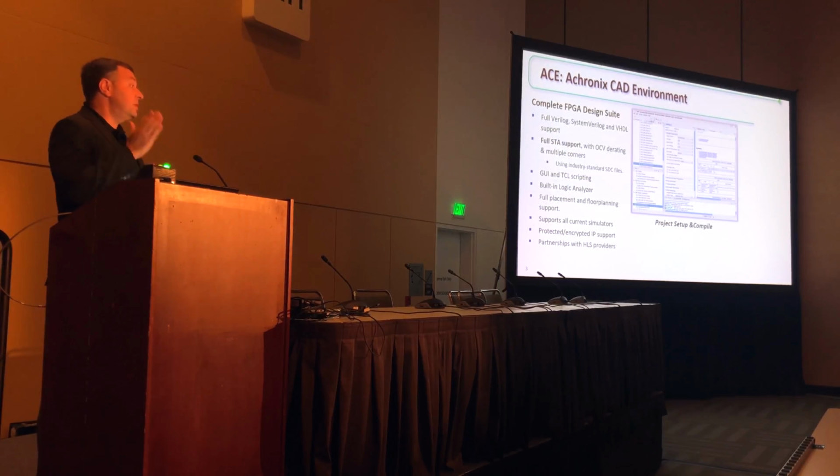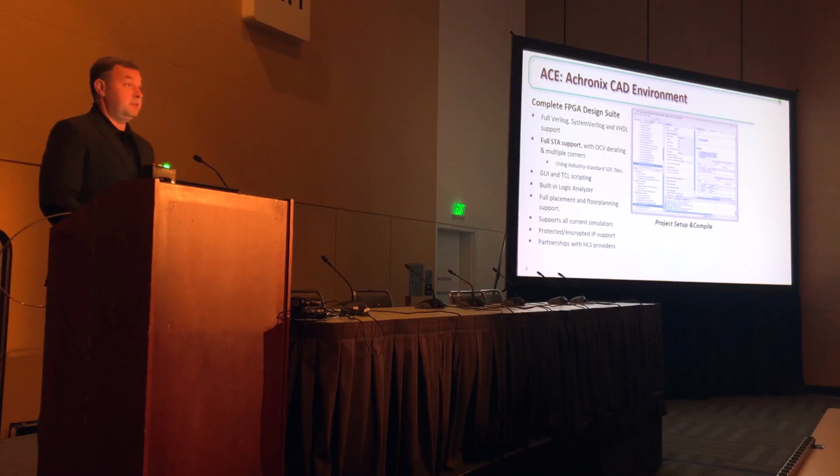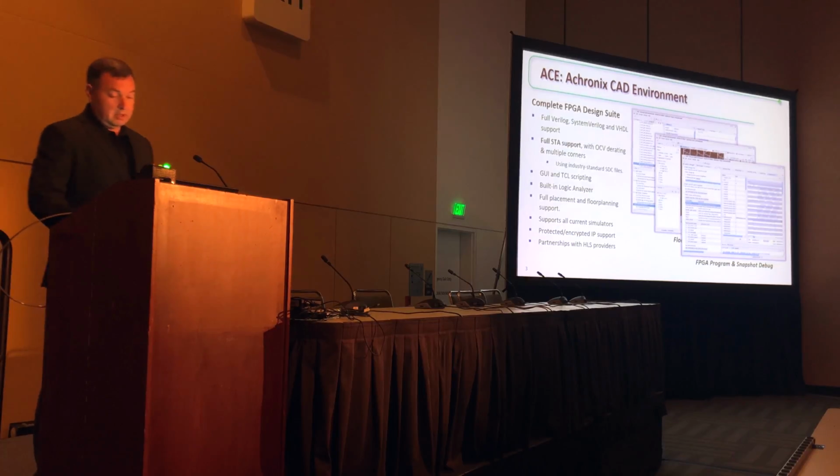We also provide a complete software environment. This is important today because we're going to be talking about timing closure, and timing closure is all about the timing analysis tools. So we provide full Verilog, SystemVerilog, and VHDL support, and full STA support, including OCV derating in multiple corners. We use industry standard SDC files, which is very important and which we'll come back to today. We also offer scripting, a built-in logic analyzer, and full placement and floor planning support. There's a picture of our floor planning tool. We support simulators, protected and encrypted IP, and we do have partnerships with HLS providers. And here's a view of our built-in logic analysis tool.